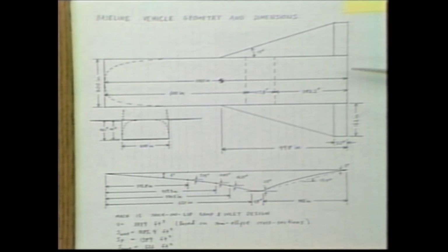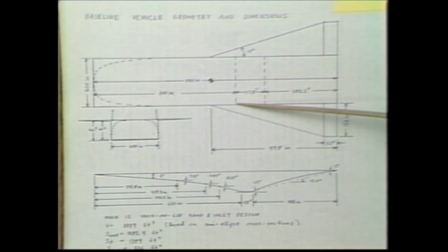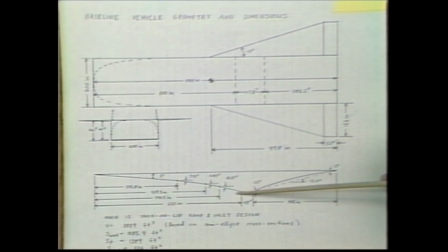1,000 inches long. Place the inlet such that I wanted to have a contraction ratio of 40 as the baseline starting point. It's about in the right range for hypersonic conditions. So at very high speeds, a contraction ratio of 40 is probably a reasonable place to start. So with that starting point, and recognizing how important it is to mix fuel and air together and how difficult it is, I kept the throat height at 2 inches. And those two design considerations basically place the cowl lip location at 600 inches aft of our nose.